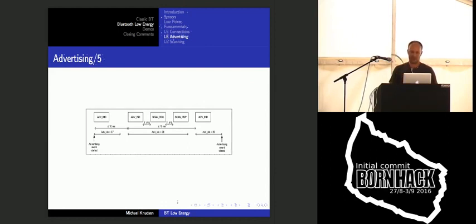This is actually a pretty good design because you can be very aggressive about turning off your radio, because you don't have to wait for maybe 10 milliseconds or just 1 millisecond for the other side to show up. He has 150 microseconds and that's it. Okay, so anyway, in this case we do the advertisement, we wait 150 microseconds, we get the scan request, then we wait 150 microseconds again, and then we do the scan response, and then we're done. After the scan response, he's not able to come and say, then I would like to connect. He has to wait.